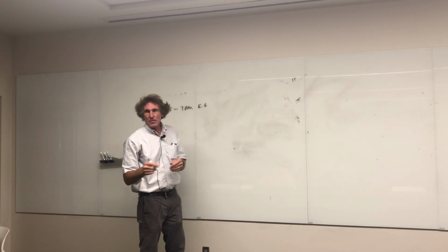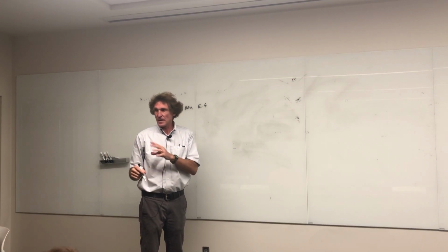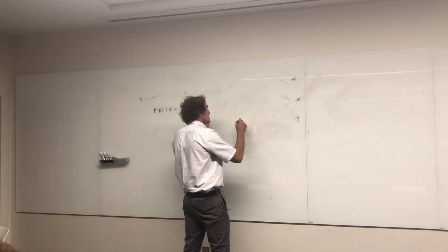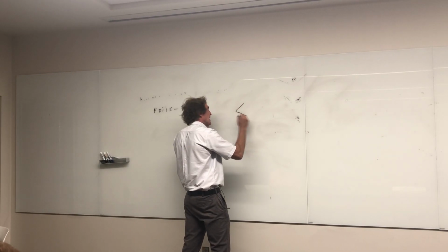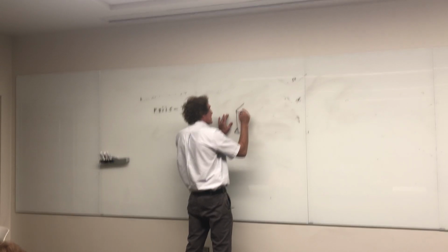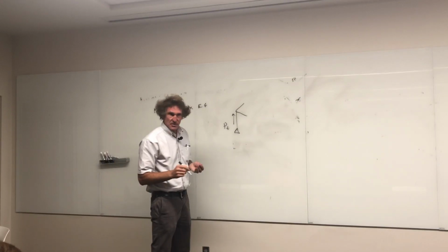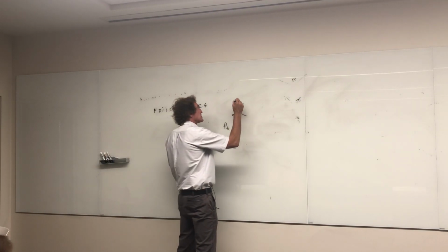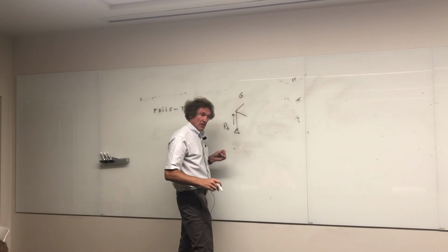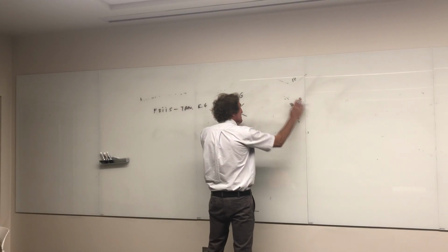And on this one, I go back to the way I typically do problems in radar and in antenna design. Now, we're going to assume that we have an antenna. This is the way I draw antennas when I teach radar, and the way the book does. And here, I'm going to say a certain amount of transmitted power in watts goes in. This antenna is going to have a certain gain, right? A gain G. And that means if I come out a distance R away,